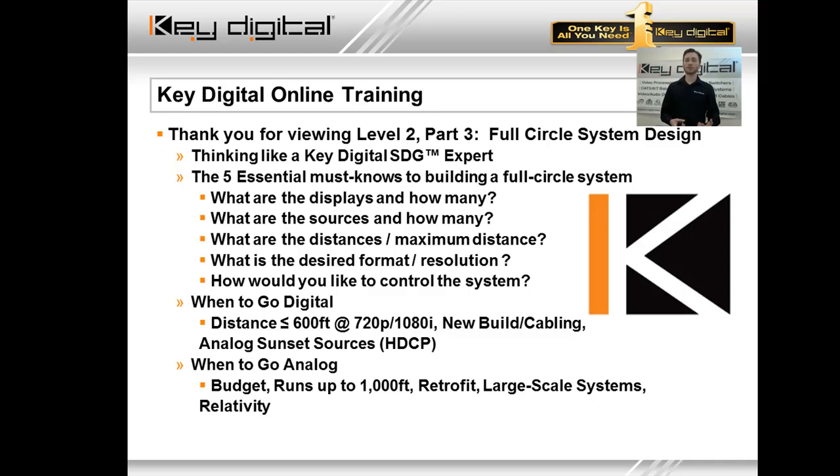Because three to four years ago, the number was about 50 feet. 50 feet we were able to deliver via Cat cabling with HDMI baluns, or even up to 100 feet at a half bandwidth resolution. So say 100 feet versus 600 feet now. Boy, the technology has come a long, long way, hasn't it? So for the distances, do you have the opportunity to run the proper infrastructure? We cannot stress enough how important infrastructure is, meaning the cabling, in the HDMI world.